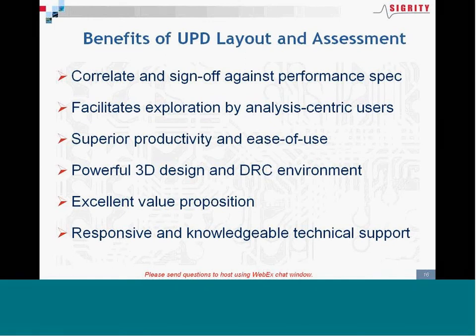Okay, I'll take a shot at that. Where the constraints come from is the values for per pin resistance and inductance are usually provided by the chip design team, more likely by an SI engineer or someone like a system architect. Now, these values are usually determined from chip static or dynamic power simulations performed for new designs. One of the other things that we see sometimes is that they're based on actual performance of known good values of previous designs, previous generation type products.